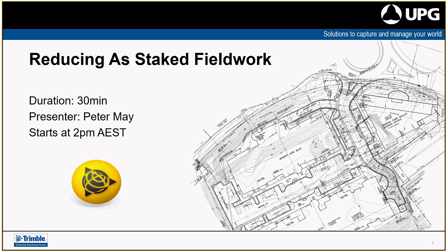So today, we're going to be looking at how to import data from your total station into TBC, and then viewing that staked out information, looking at the delta values against the design points that you would have uploaded when you went out into the field. It's just a bit of a run through how it would be done. This is one workflow, so obviously it's not the best, and there are multiple different ways of doing it.